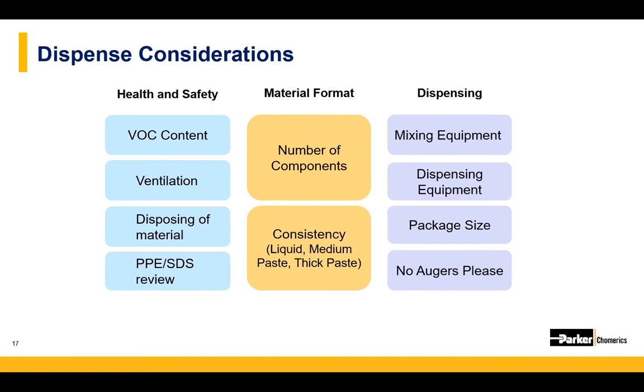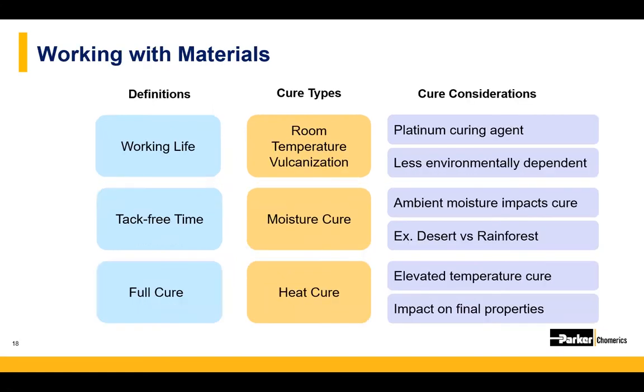Ben, are there any types of systems to avoid or steer clear of? Because we want to minimize the damage to the particles and protect the plating on the metal particles that give us that good electrical contact, we urge customers to stay away from auger valves or auger style systems that can actually shear the material. Good to know.